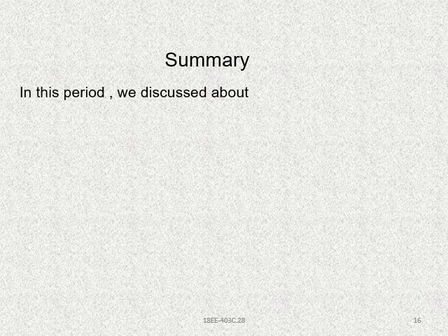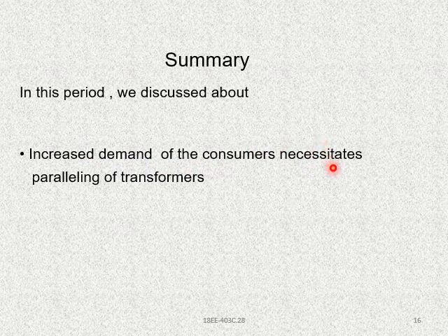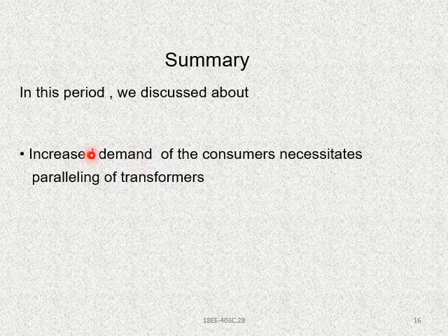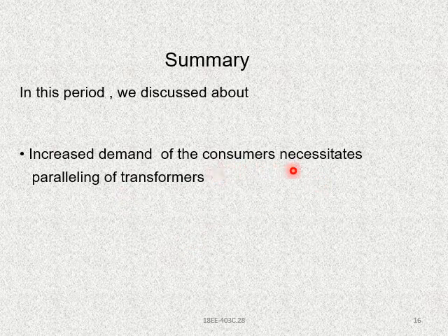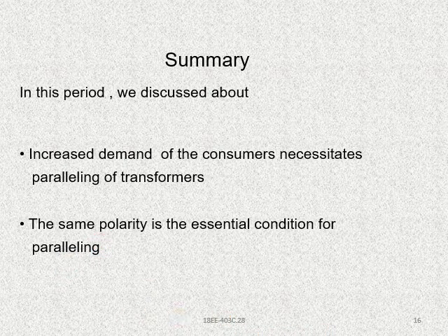So in this class, we have discussed that the increased demand of the consumers necessitates paralleling of transformers. As I said previously, when the demand increases, the transformers should be connected in parallel to meet the consumer's necessities. The same polarity is the essential condition for paralleling.